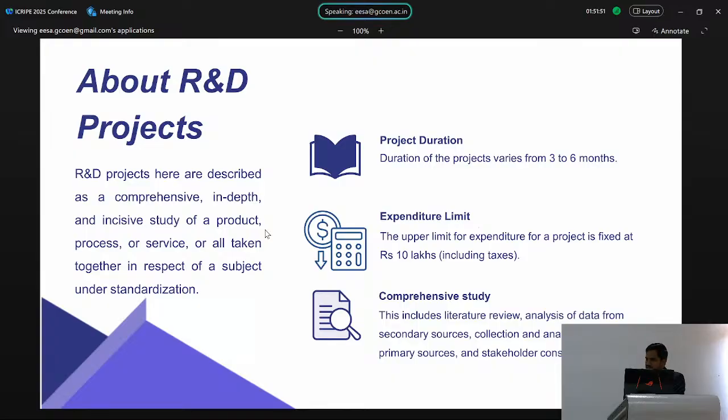Although it will have a low cost, it will not have proper strength. And if someone uses a lower content, that will not be a cost-effective process. So there should be one exact percentage depending upon the usage of that PVC pipe. For different classes, a different calcium carbonate content is the optimum content.